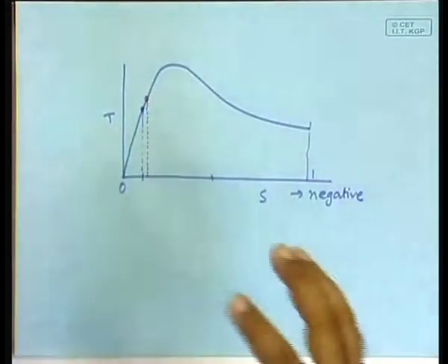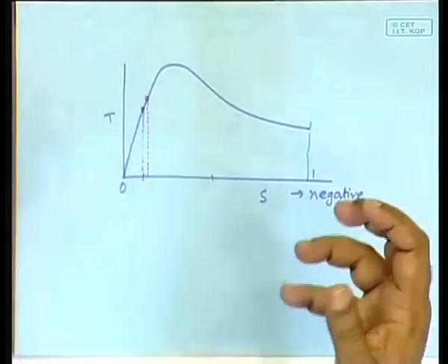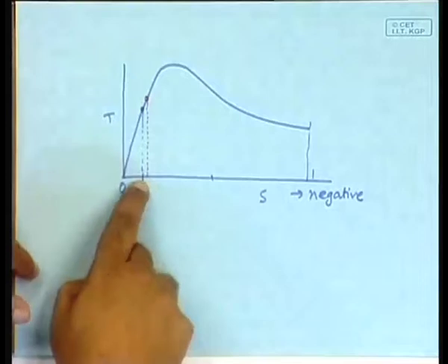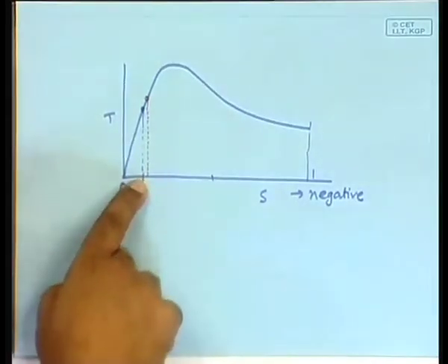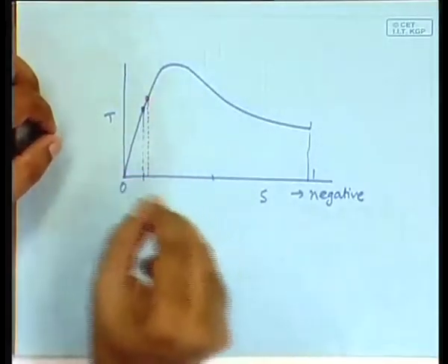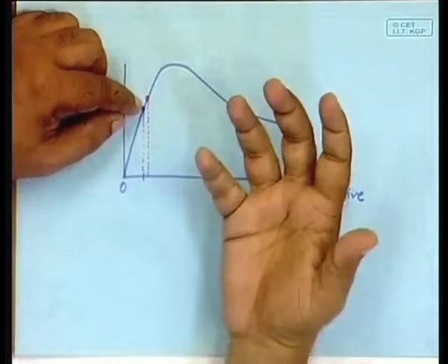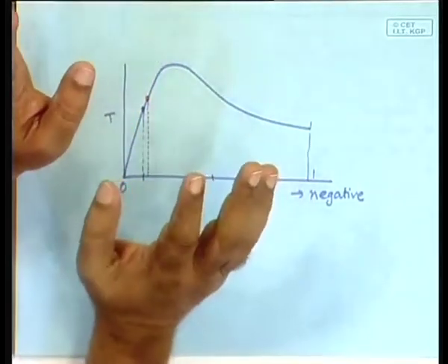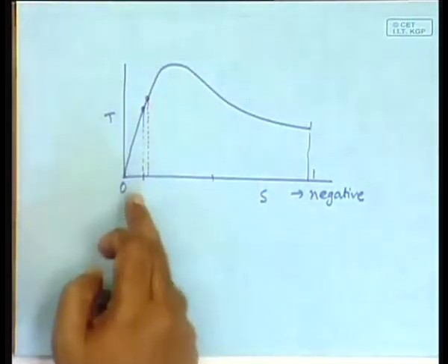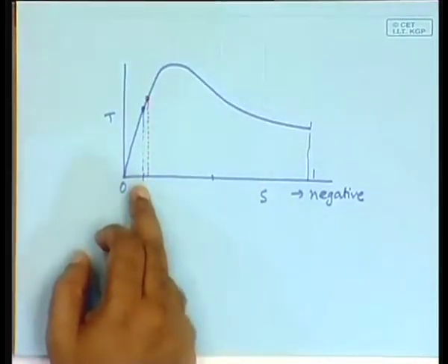Okay. The wind turbine was giving a certain amount of torque, and due to some reason the slip increased, and what has happened? The back torque has increased, right? A back torque has increased means it will slow it down. As a result, the slip will again come back to this value. Can you see that? There was a torque given by the wind turbine, and when it is working here, if somehow the slip is perturbed, then the torque is perturbed in the direction which will bring the slip back to its normal value. Is the statement clear? Which means this is a stable mode of operation. It is a stable mode of operation.